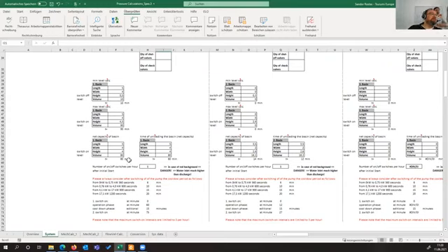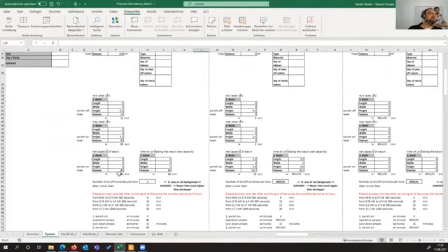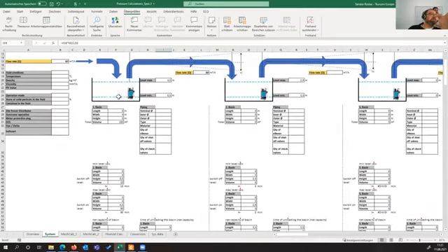So under these conditions, but this is not really true because we still have not defined, oh, it is true with 80 cubic meter per hour. Sorry, there was a number already. So what will happen if we change this number to 60 cubic meter per hour outlet? So we still need 80 minutes. So this is the time of unloading of the basin, of the net capacity. Net capacity means the level between max and minimum.